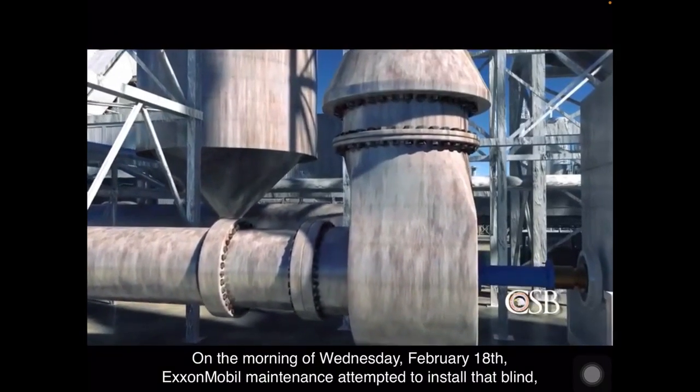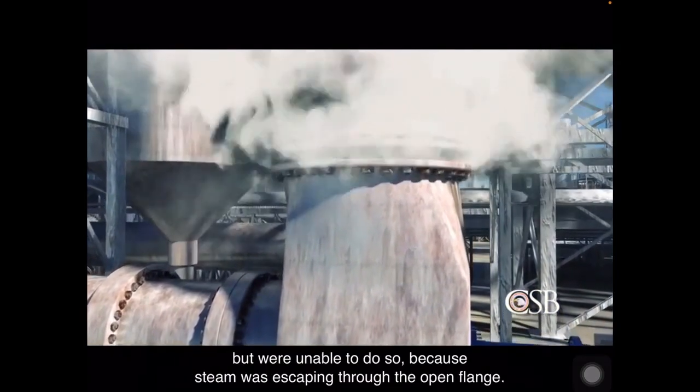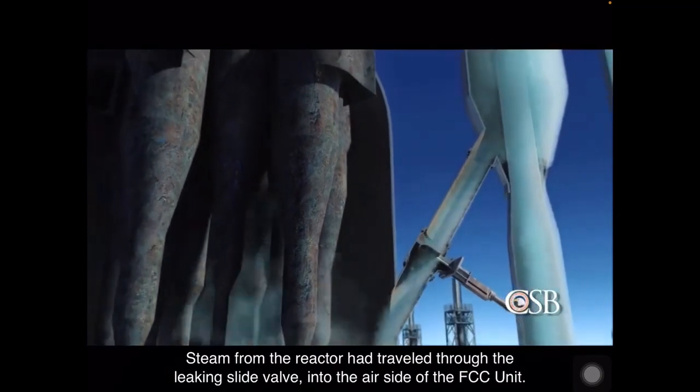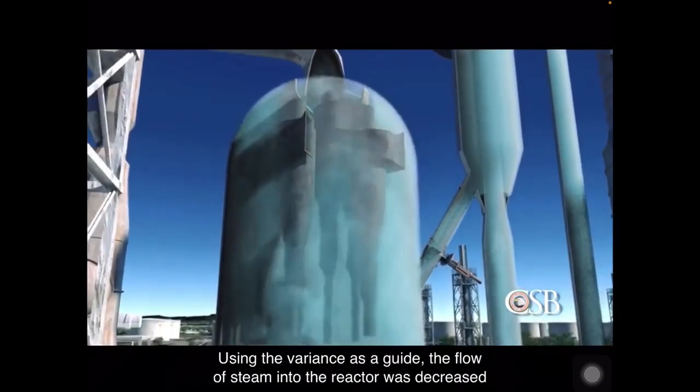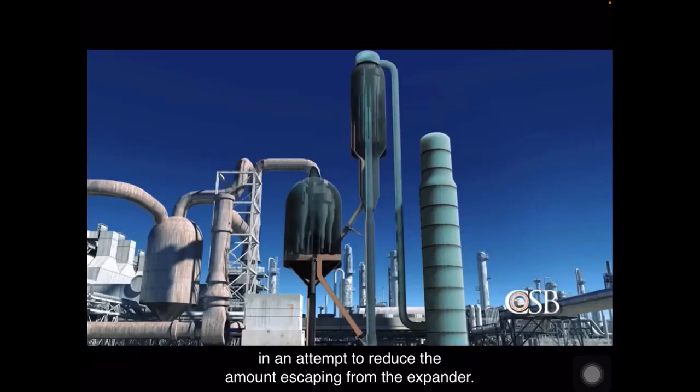On the morning of Wednesday, February 18th, ExxonMobil maintenance attempted to install that blind, but were unable to do so because steam was escaping through the open flange. Steam from the reactor had traveled through the leaking slide valve into the air side of the FCC unit. Using the variance as a guide, the flow of steam into the reactor was decreased in an attempt to reduce the amount escaping from the expander.